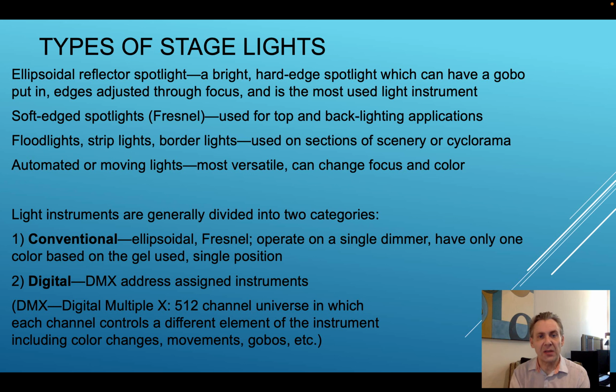A theater space can have more than one universe. So, I know this is confusing. Here's what happens. When you hang a digital instrument and you plug it in, you don't just plug it into a power source. You also have to plug it into a digital universe. And you have to know if it's going into universe 1 or universe 2 or universe 3, however many universes that theater environment is wired for, because it has a max of 512 channels.